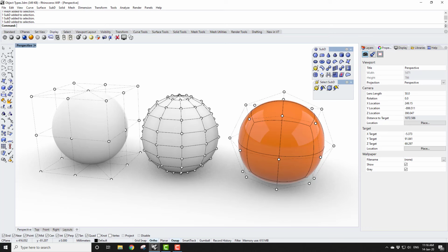Rhino's new SubD objects can be created in a number of ways. Surface commands such as Loft, Revolve, Sweep 1, Sweep 2 and Extrude all have the option of creating SubD output. Curve commands have SubD friendly options, and of course there's a number of primitives. There are also workflows where meshes can be converted into SubD objects. Finally, Rhino SubD objects can be losslessly converted to NURBS objects.